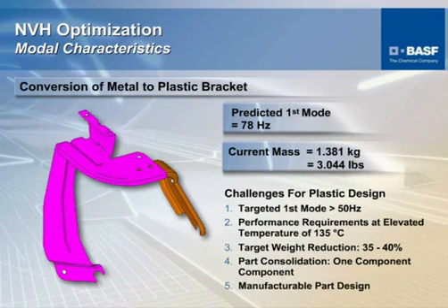Bracket, we were converting the metal to a plastic bracket. We had to basically design it so that the target first mode was greater than 50 hertz. We had to do it at certain temperature levels and meet certain target weight reductions.